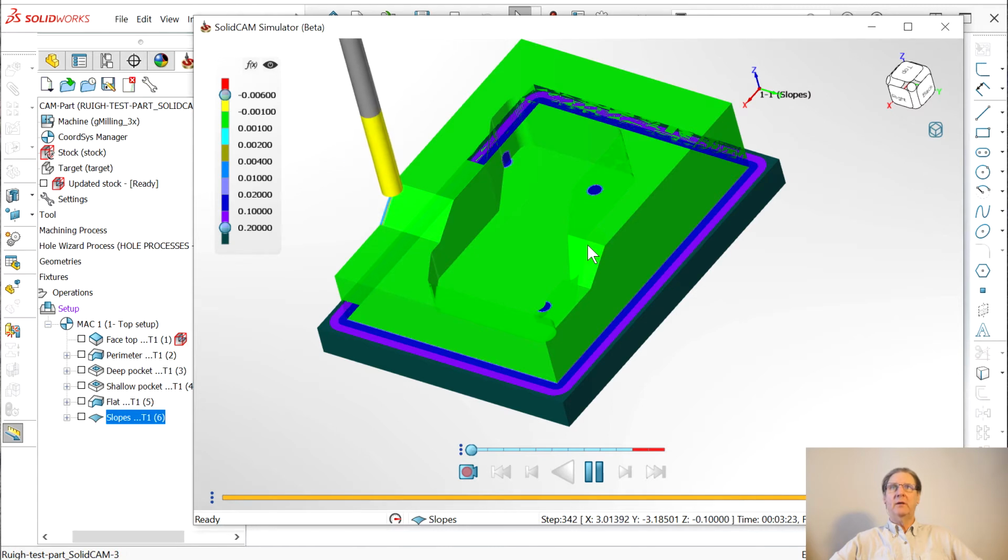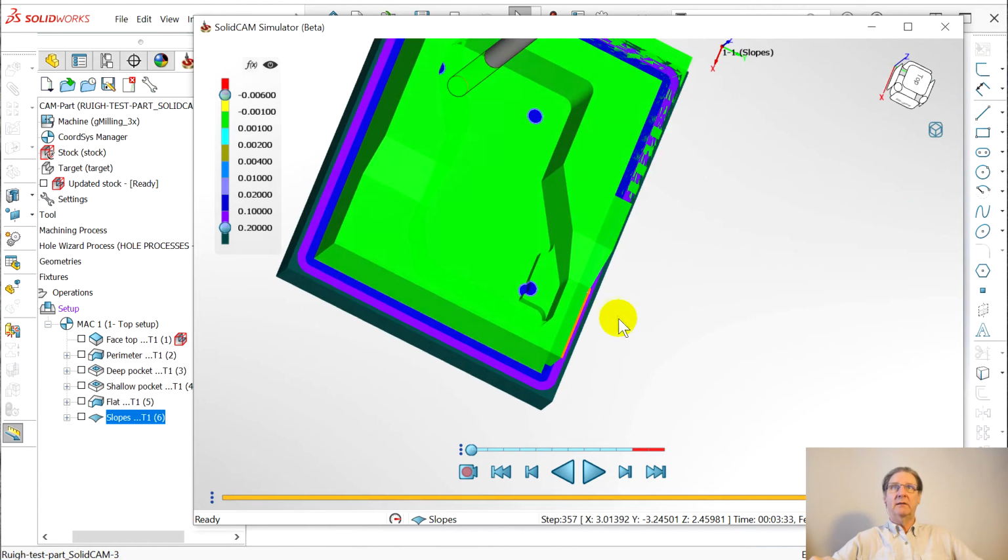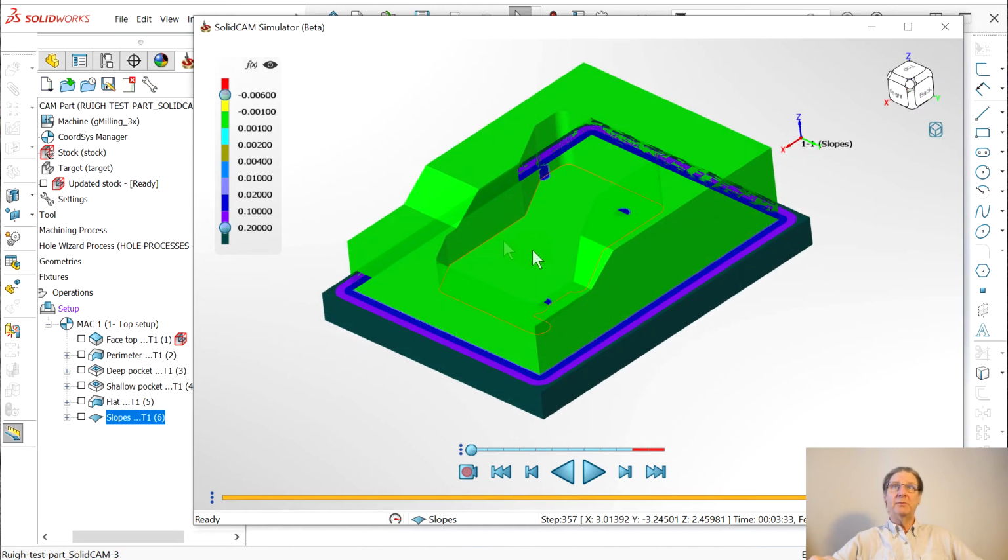You get a lot of power. What 3D to them means is iMachining 3D. And that's a big deal, where it's adaptive tool paths and no hard corners in the tool paths, all swoopy. But you notice it's within 1,000th of an inch everywhere now, right? That was my buddy's genius. No, use the ball mill.